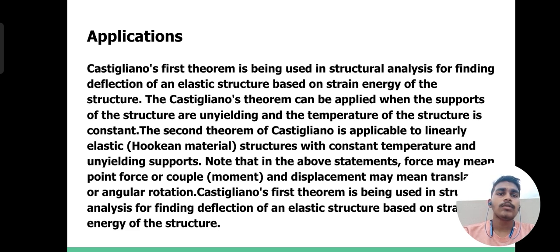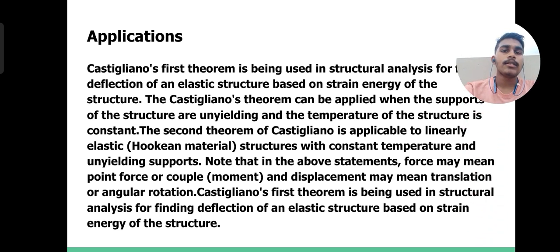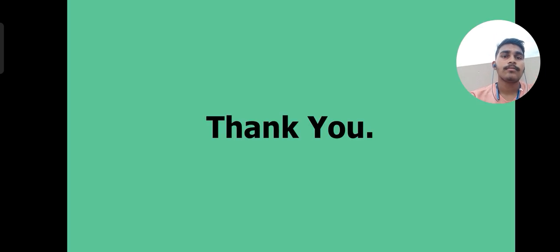and unyielding supports. Note that in the above statements, force may mean point force or couple moment, and the displacement may mean translation or angular rotation. Castigliano's first theorem is being used in structural analysis for finding deflection of an elastic structure based on strain energy of the structure.